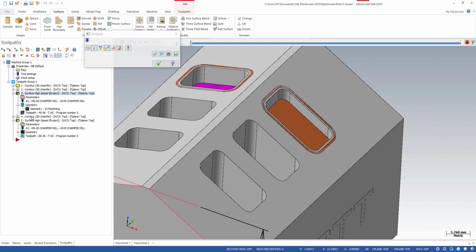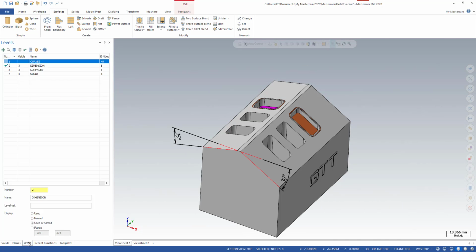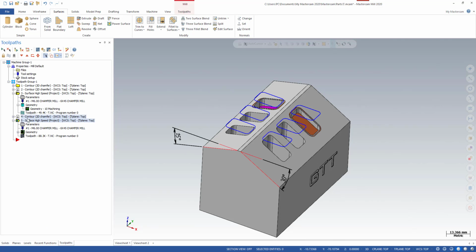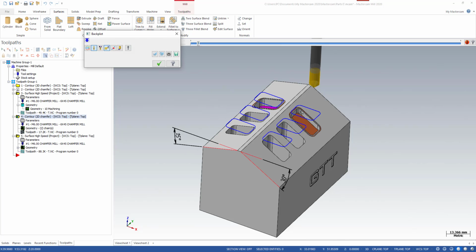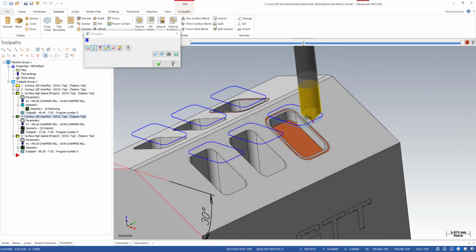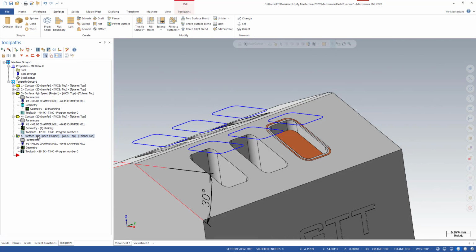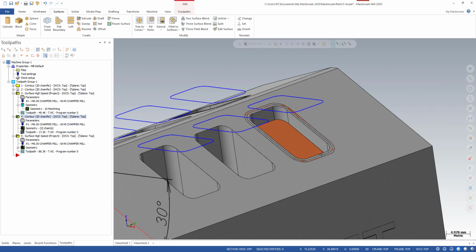Let me show you. This project toolpath also uses the NCI data from the 2D toolpath, 2D chamfer. This is the number 4 here. You can see I use a 3D contour, 3D chamfer for making the toolpath, making the NCI. And the next toolpath, the project, will use the NCI data from this toolpath and project it to the surface we selected. Okay.